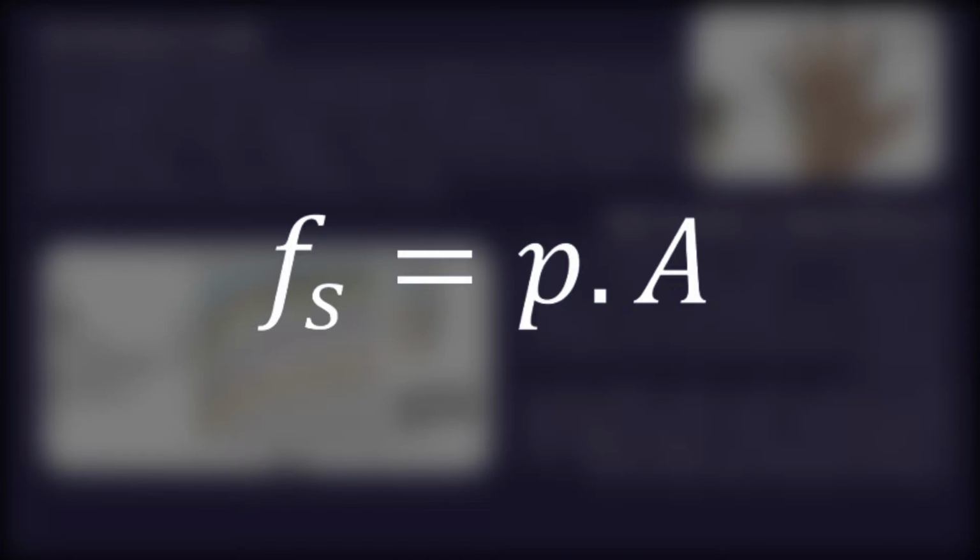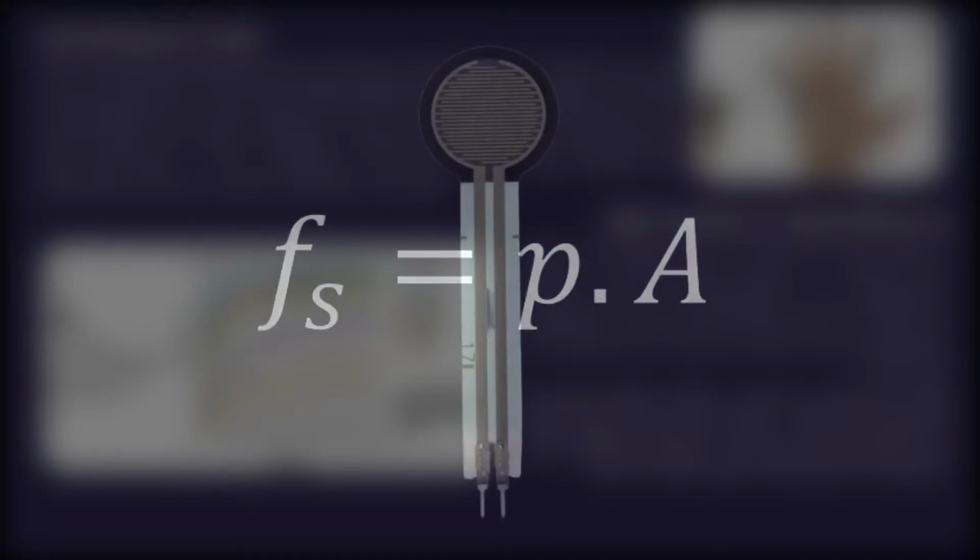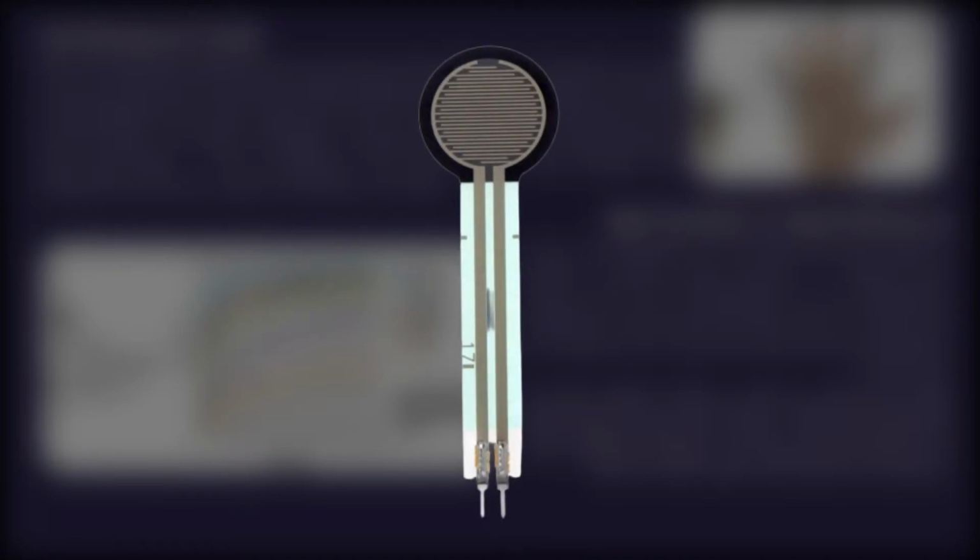From that principle, I use a film force sensor called FSR402. The FSR 402 sensor is utilized in control and robot applications such as pressing buttons, measuring clamping force on robots, detecting pressure at one point, and so forth through the detection of resistance changes.